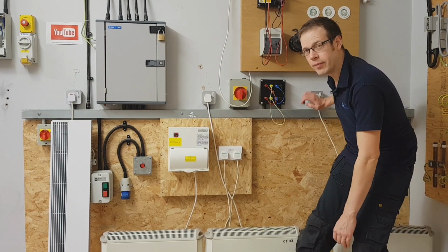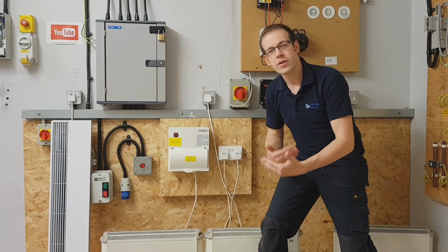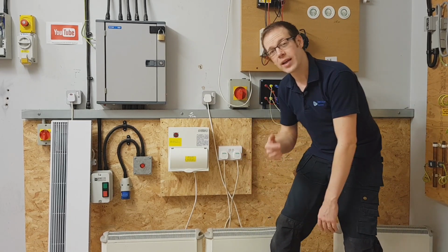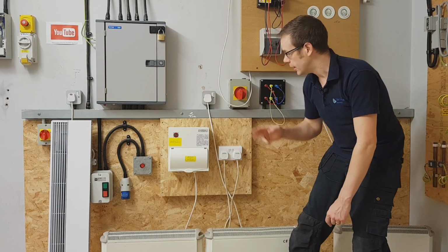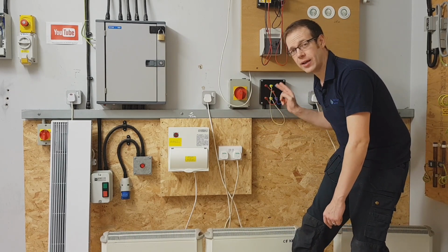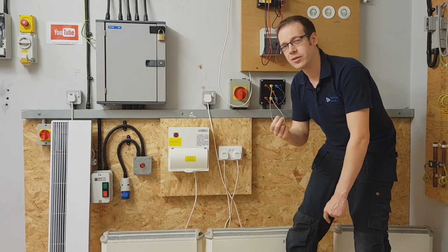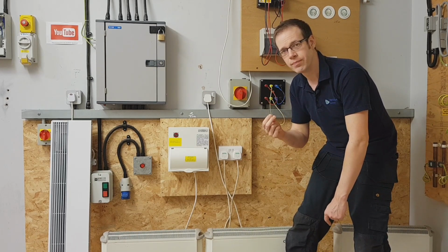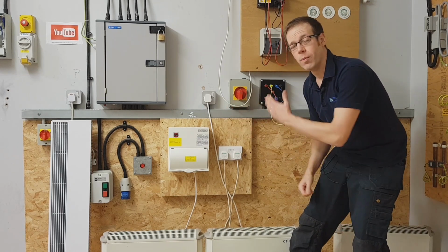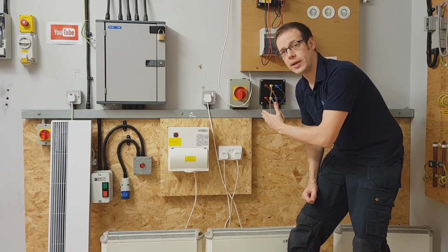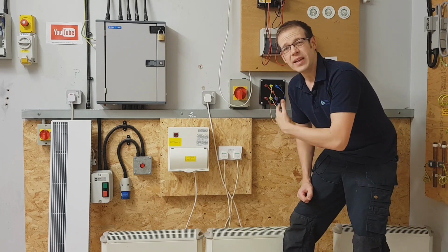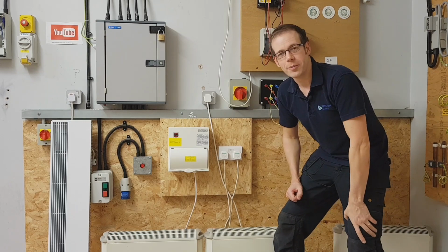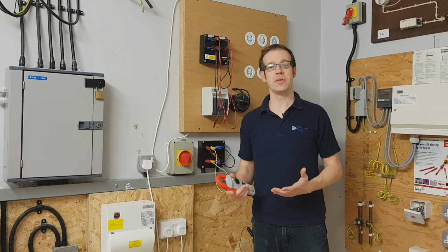And then over here, we've got our third load, a 2 kilowatt load, and that is connected into L3. So you can see there that we've got three different size loads connected to L1, L2 and L3, which means that we're going to have different levels of current flowing through L1, L2 and L3. And that's what we mean by an unbalanced three-phase load. Different currents inside those conductors. So we'll power the heaters up, we'll measure the currents in L1, L2 and L3, and then we'll measure the current in the neutral, and then try and figure out why the neutral current might not be quite what we're expecting it to be.